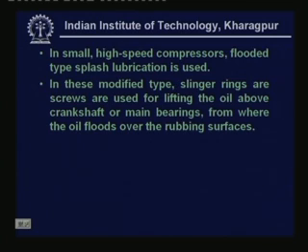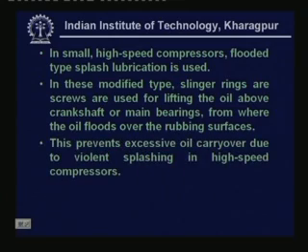If you are using a splash type in high speed compressors, then a lot of oil may be thrown, okay. So this may create oil carryover problems, okay. So in such cases, they normally use a helical screw which will carry the oil, okay. So the oil carryover is reduced. So this prevents excessive oil carryover.